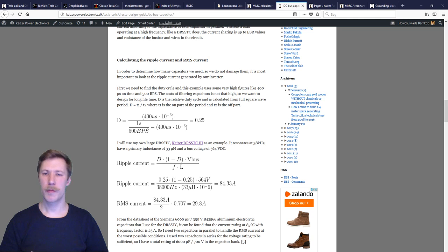So this gives a much more aggressive current delivery ability to the inverter. I also know from Gizmo, who built large Tesla coils, that he mentioned you don't even need as much DC link capacitance when you are using MKP capacitors, simply because they can deliver so much higher peak currents.